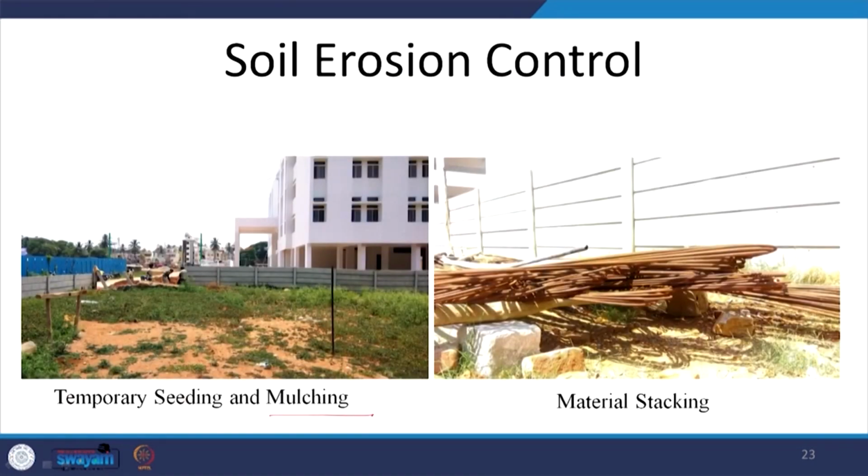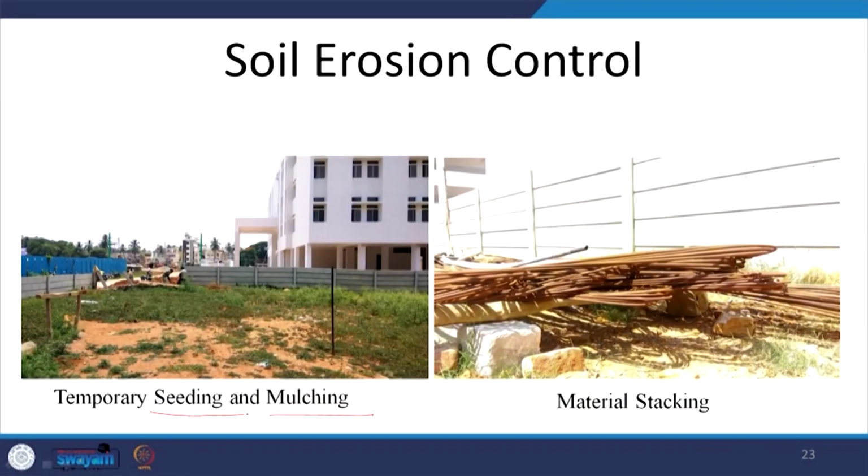Temporary seeding and mulching we have already seen, not just for slopes but also for plain areas. The soil which is stacked, which is coming out of the excavation for large building projects, it may be seeded and mulched temporarily, but it will help in controlling the soil erosion. And then proper stacking of materials. Many a times, because the material is not properly stacked, it disturbs the compactness of the soil, it makes it loose, and that is what also increases the soil erosion.